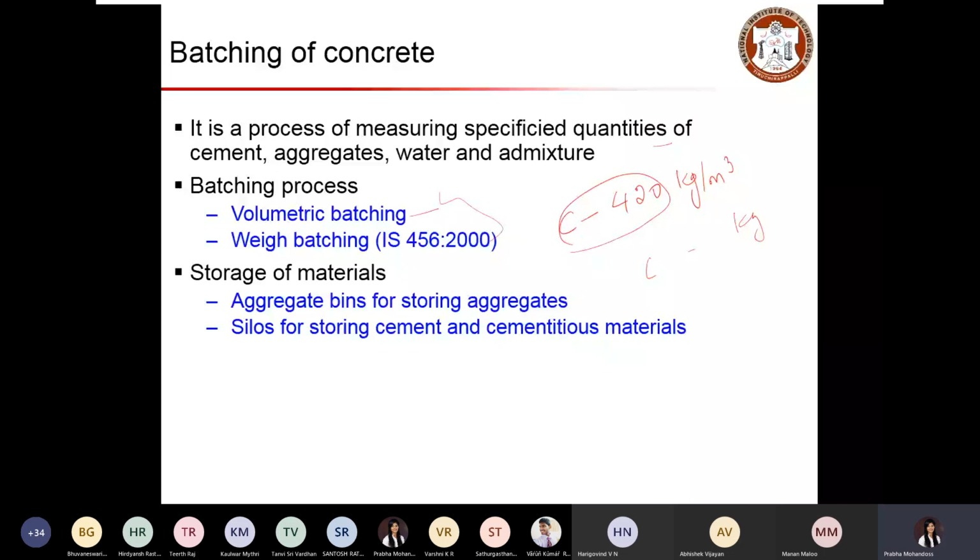So one container of this will be fine with respect to half or two containers of cement or the water. This proportion is based on the container, and again this varies from person to person, because some may compact or accumulate more aggregates or more cement in the same volume of container.